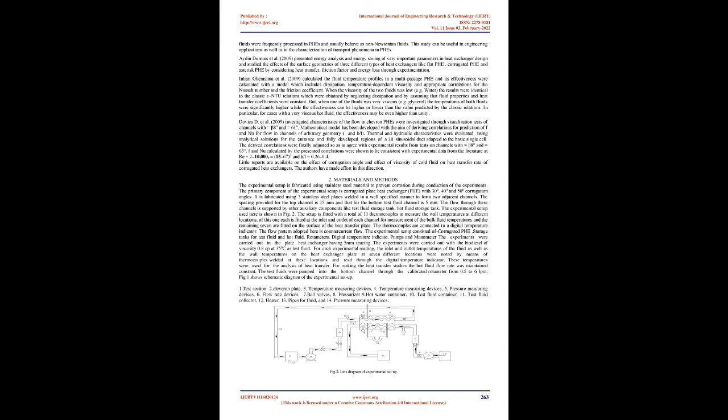Anil Kumar Dwivedi and Sarat Kumar Das, 2007, presented a predictive model to suggest the transient response of a PHE subjected to a step flow variation. The work also brings out the effect of the port-to-channel maldistribution on the performance of PHEs under the condition of flow variation. The results indicate that flow maldistribution affects the performance of the PHEs in the transient regime. A wide range of parametric study has been presented which brings out the effects of NTU and heat capacity rate ratio on the response of the PHE subjected to flow perturbation. They carried out experiments to verify the present theoretical model.